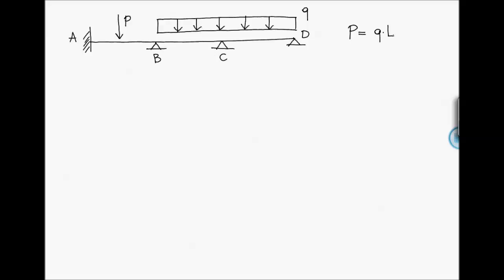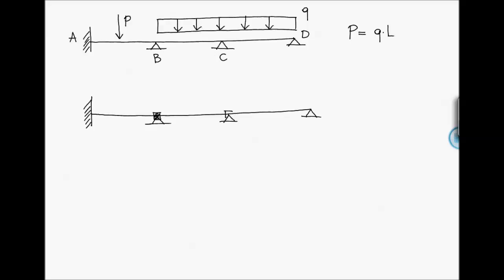So when we apply the Cross method, we have to consider the fixed end moments coming from the structural scheme in which we lock the rotations in node B and node C. Actually, these rotations are not the unique displacements we can have on this structure, since we can also have a rotation in node D. Here we add the additional restraints only in nodes B and C, since the structural scheme of beam CD loaded with a uniform distributed load is known.